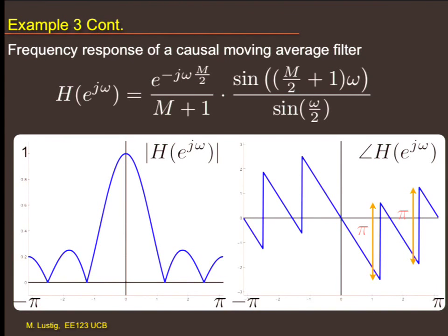Go for it. Sign change. That's right. So if you look at the periodic sinc, the periodic sinc should have had a sign change. And if we took a magnitude, we moved that sign change, which is 180 degrees, turns out to be also pi, into the phase component. Okay? So sometimes we'd like to see that pi. Sometimes you'll see later that we're going to create functions that don't have this pi change, but then have a sign change here. Okay? So it's not going to be a magnitude thing. Okay? But we're going to see it later. But the pi shows up whenever there's a zero crossing of that function. Okay? All right, fantastic. That's great.